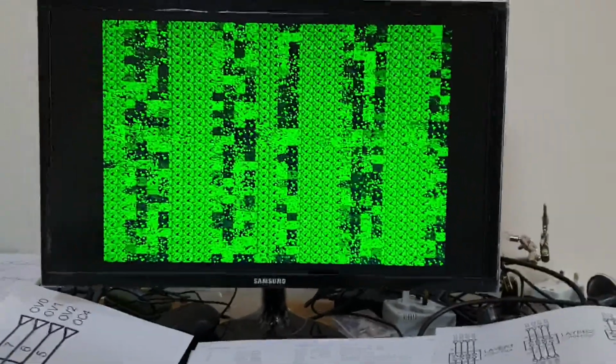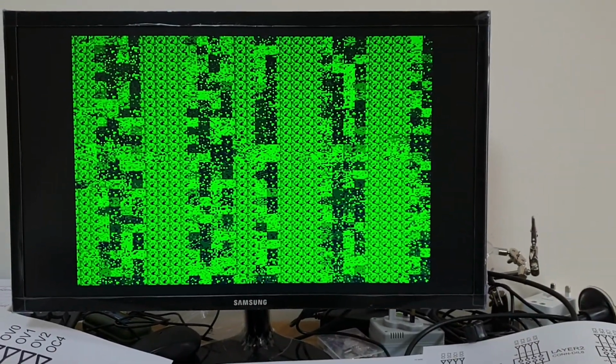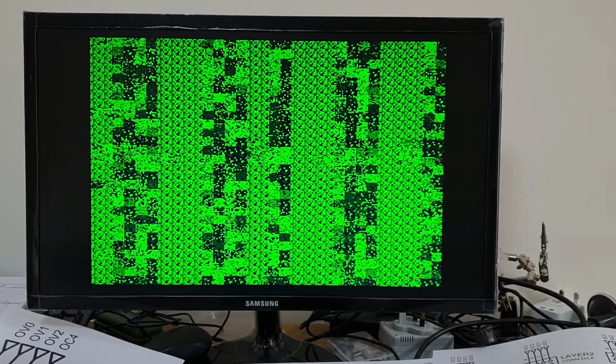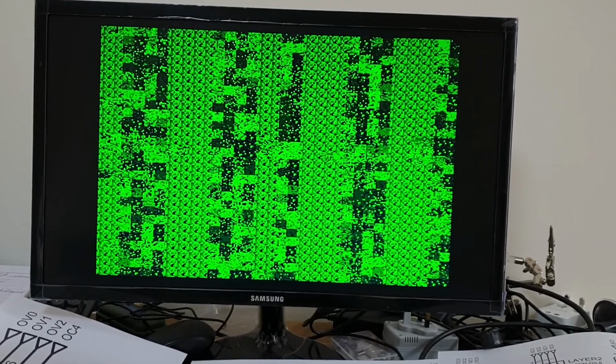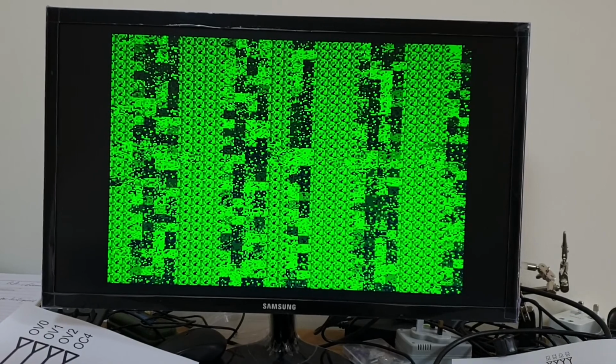Strangely enough, the first 2 lines in the RAM, although they're connected up in the schematic, are not actually output because there's a top and bottom border. So anyway, 9040 in hex should be the top left-hand corner of the screen.